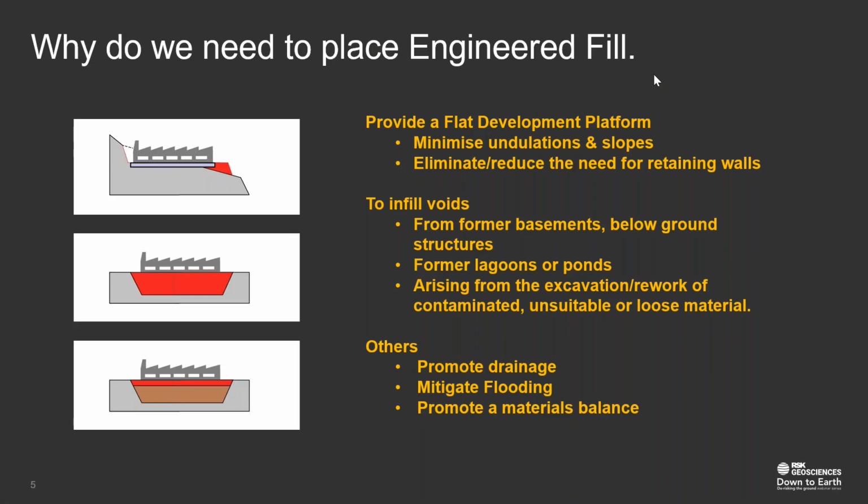As engineers and developers, we are rarely happy with sites when we find them. For a variety of reasons, we often want to change site levels, generally to achieve a flatter site and a cut-fill balance. Necessarily, this involves filling to a greater or lesser degree. This fill will need to be at an appropriate standard for its end use, i.e. beneath structures, infrastructure or landscape areas, and the requirements for each of these will vary.